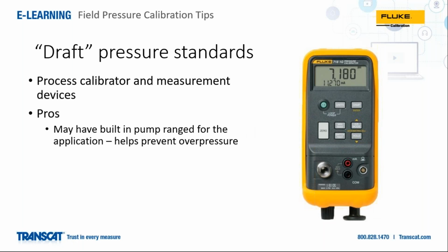A lot of the parts here are pretty common, like this manifold fitting on here. This is the same fitting on all the process calibrators. This thing's the same. However, the way that the pressure sensor connects to the fitting and the way that the pumps work together can be different. So it's not always the case that you can just swap out one for one.